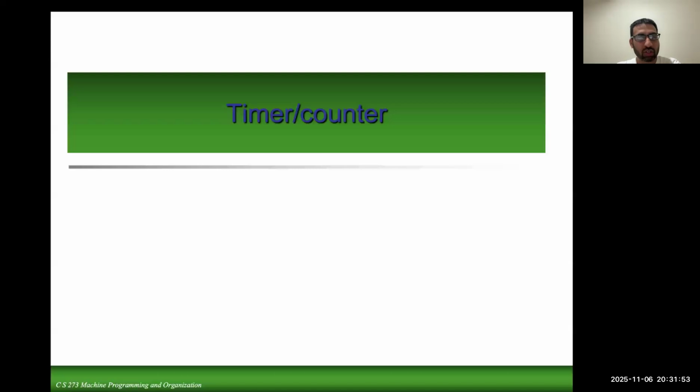The registers which we mentioned were the timer counter register 0, which is actually used to hold the initialized value, which is incremented on every clock. Other than that, we have control registers, two control registers per timer or counter. And also we have two output comparison registers for each timer or counter, which are named OCR0 for timer 0, but there are two copies of the same output compare register, and they are named OCR0A and B, right?